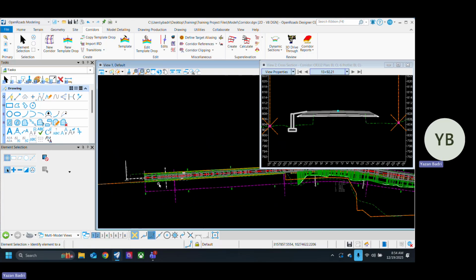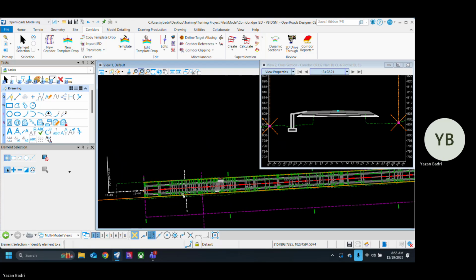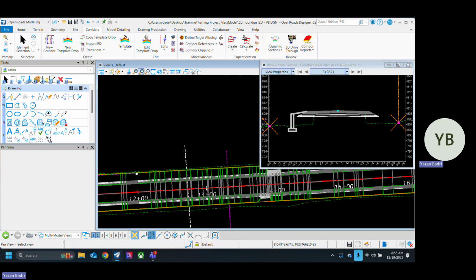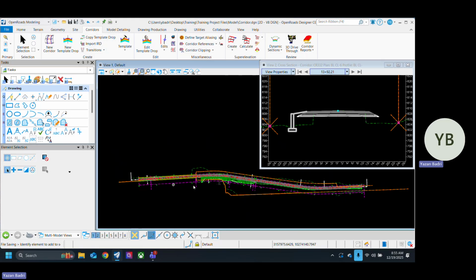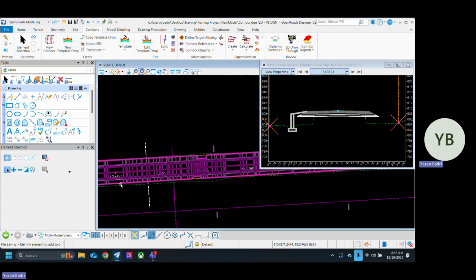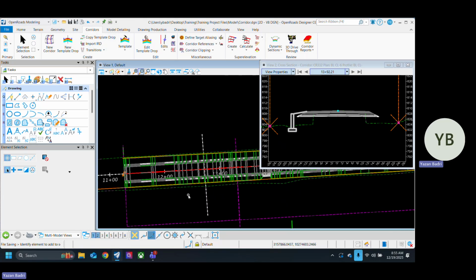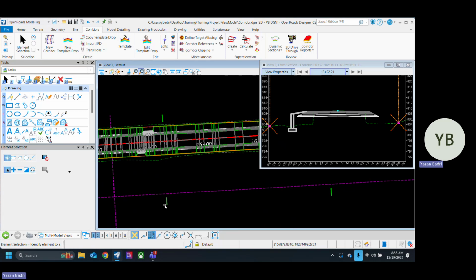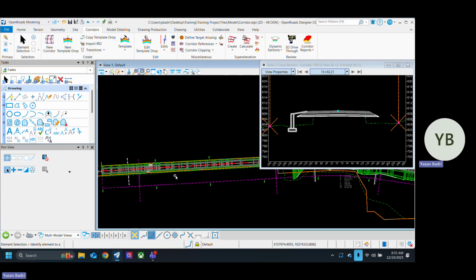But when you have point controls, it adds a lot more to make sure that it's tying in how you want it to tie in. Point control will do that too. It just automatically does that. Did it change from preliminary to design, or did it remain unchanged, but just added cross sections? So regardless of the stage, it still added cross sections. Okay. Because it wants to do what it's supposed to be doing, which is tying into the right of way.